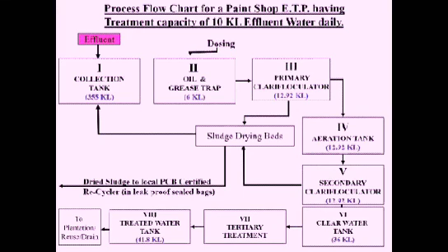Again at the bottom there is a conical chute, and from both primary and secondary clarificators, the comparatively denser effluent collected at the bottom conical chutes we connect to the sludge drying beds, from where the dry sludge from the top surface is collected and put in leak-proof sealed bags, maybe HDPE bags or containers, to send to the CPCB or State Pollution Control Board certified recyclers.